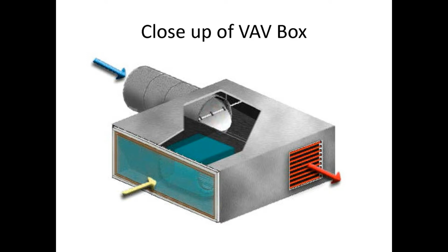And even in the wintertime, you're most likely going to be running the air conditioner. All right, so in this design, a VAV box is very inexpensive, and each VAV box gets its own thermostat. So you could have 100 thermostats in this building if you wanted, and it wouldn't be that expensive. So that's another concept that we have to choose from in HVAC design.